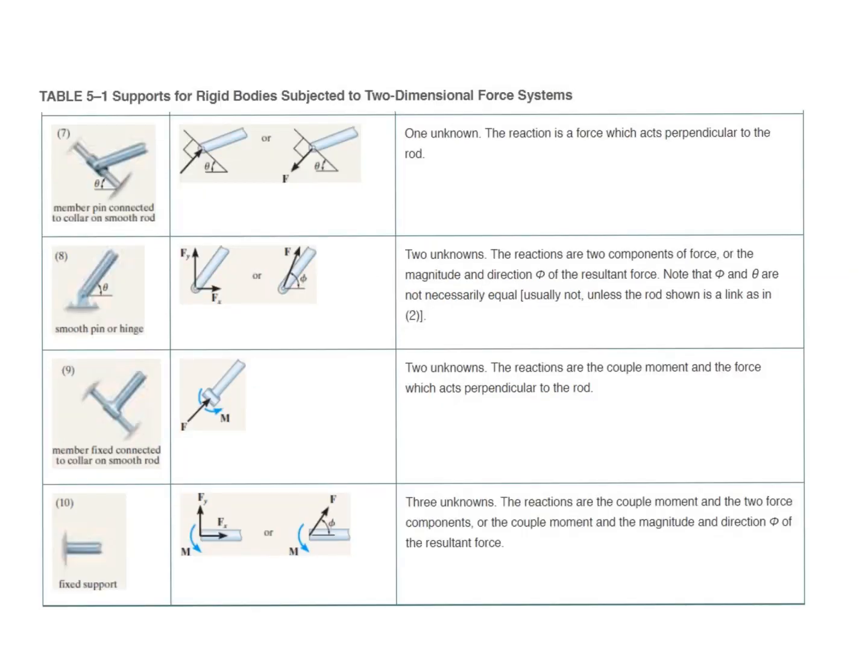In this seventh type, we have a little collar that is sliding on this pipe support. In the ninth type, we have a similar arrangement. We have a collar that can slide on this little pipe support. But the difference between seventh and ninth is that in the seventh, the structural element is pinned to the collar, whereas in the ninth, the structural element is welded to the collar. So in the seventh, the structural element can slide in that direction and rotate about that point effortlessly, whereas in the ninth, it can still slide in that direction effortlessly, but you cannot rotate this.